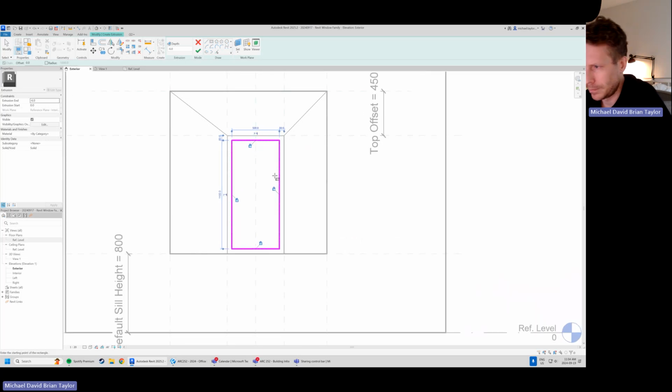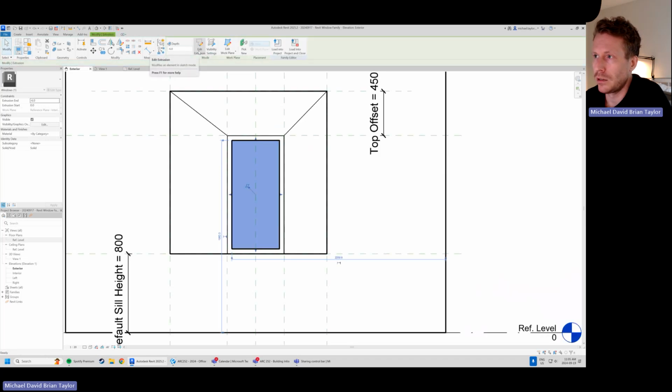I think this is going to work for now, and I'll show us some examples of what we need to get to. So hit that little check mark button to finish the overall extrusion model. Let's hit finish mode. Here we go. Great, right? Before we do anything else, one thing about Revit is it doesn't know what this material is. Because we know that this is glass, we need to tell Revit that the material itself is glass, that way we can see through it when we see the model. This is going to be an important step because otherwise you're going to have a blank, opaque surface that Revit won't be able to tell is supposed to be a window.